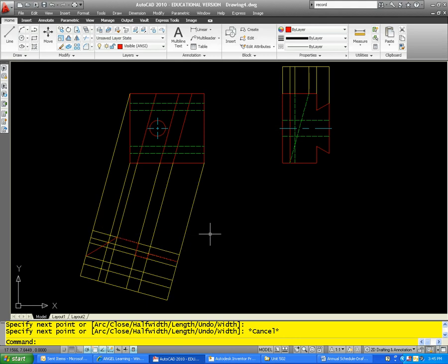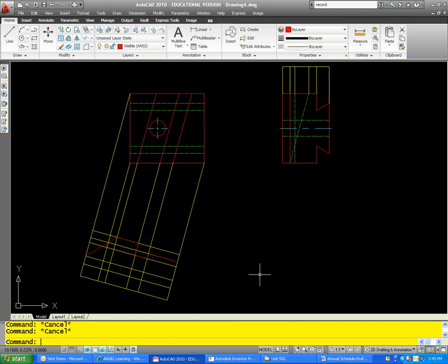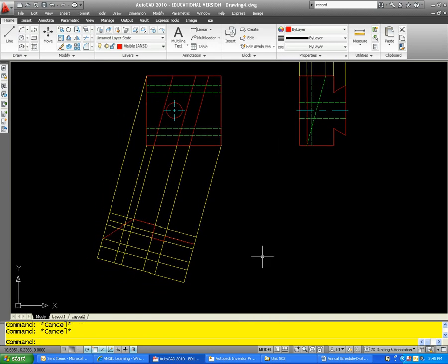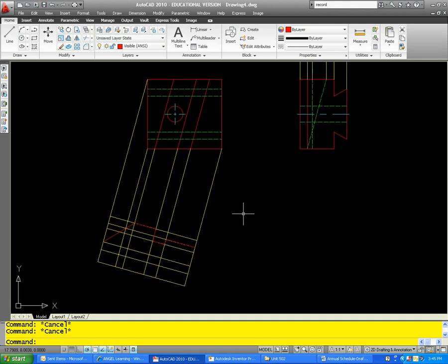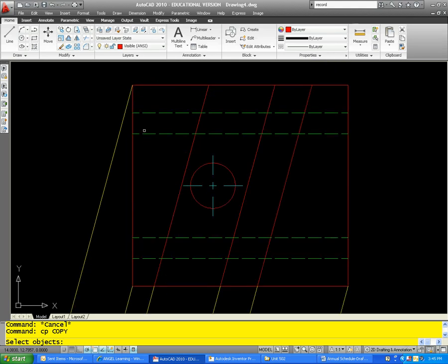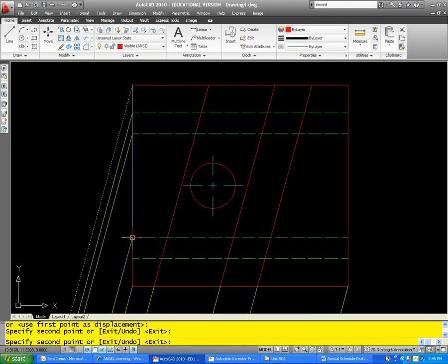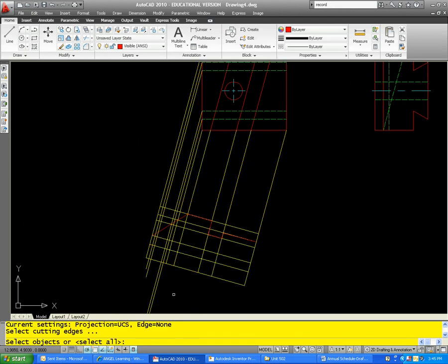So that's what the top outline of the development looks like. Now it gets a little bit tricky. Okay, but to work on this side, we need to account for the hidden lines here on the bottom. So let me copy those around, and I'll trim off the excess here. Okay, now